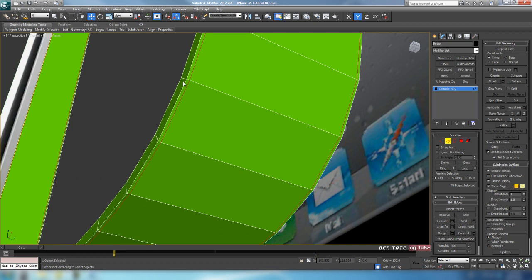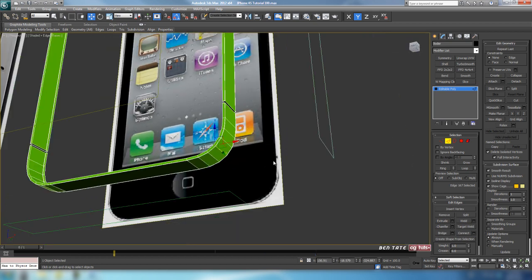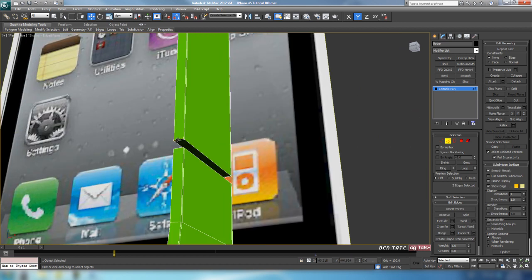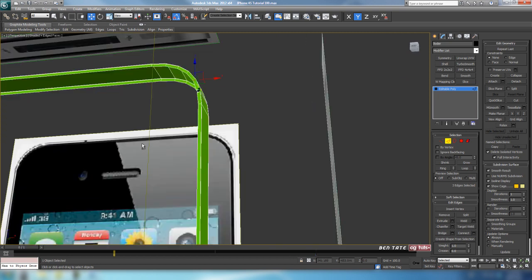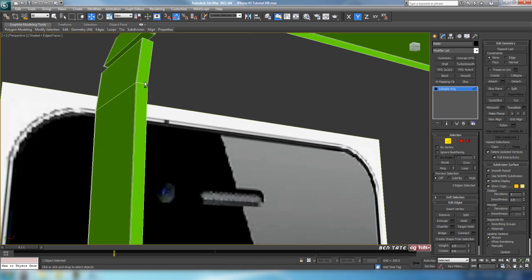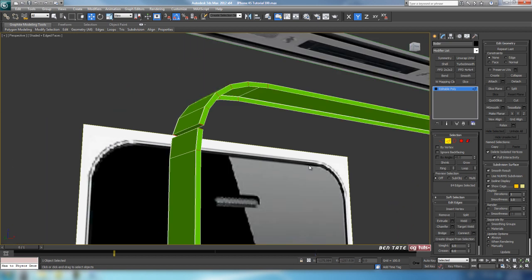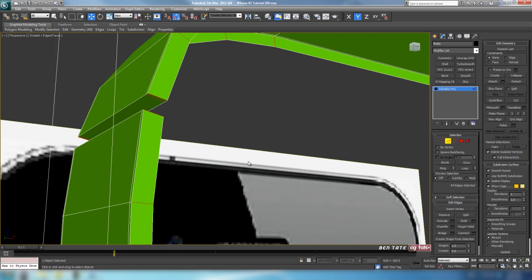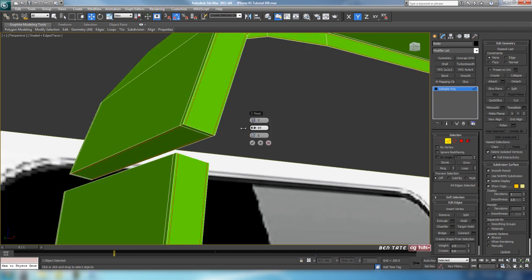And we actually need to add that on the outside as well, so I'm just going to grab an outside edge there. Let's actually grab one on each of these pieces. Should have done this first before I broke it up, but that's okay, it only takes a second. Okay, so let's do a ring. Okay, now select all the outer edges on the front and back. Alright, so we'll do another connect here. And we'll dial this back a bit, we don't need to be that tight. Let's do maybe around 65 or so, and let's hit OK.